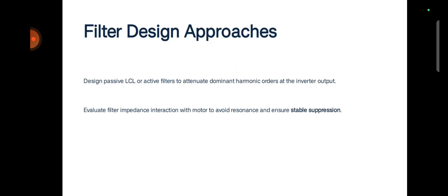Mitigation techniques. Filter design approaches: design passive LCL or active filters to attenuate dominant harmonic orders at the inverter output. Evaluate filter impedance interaction with the motor to avoid resonance and ensure stable operation.